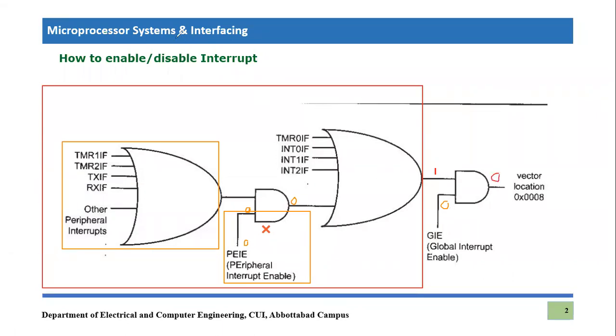So this input is very important. This is called GIE, global interrupt enable. This bit is very important, and if we make it 0, that means no notification will eventually arrive to our system, right? And how can you make it disabled or enabled? By putting here 1 or 0, right? This is the key area where we have to focus, and be very careful in putting the value.